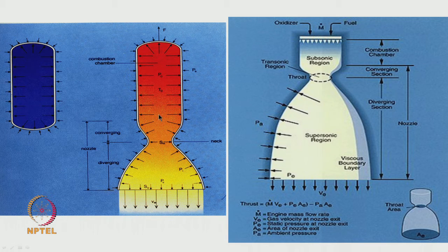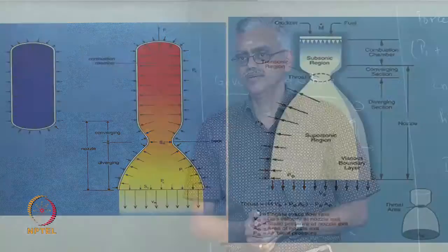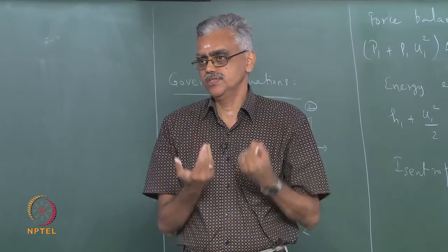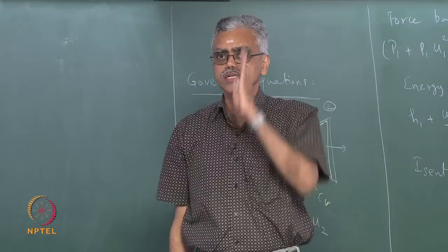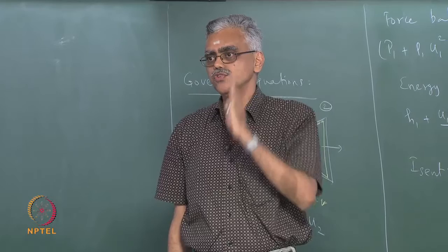So you can actually see, it is quite interesting to see from this that, remember, if this were to be used in a rocket, in which direction will the thrust force be developed? Thrust force should be developed upwards, correct? But you notice that the convergent portion of the nozzle actually develops net thrust force in the opposite direction. So the convergent portion of the nozzle actually produces drag. It is only the divergent portion of the nozzle that produces thrust, because after I subtract this ambient pressure from these arrows, now I have a substantial component in the flow direction which produces thrust.